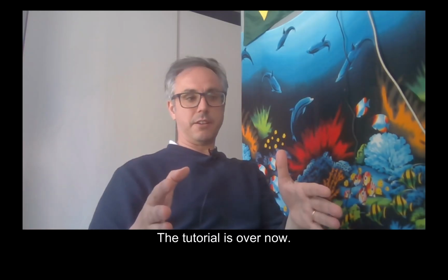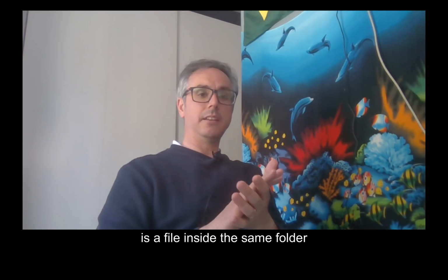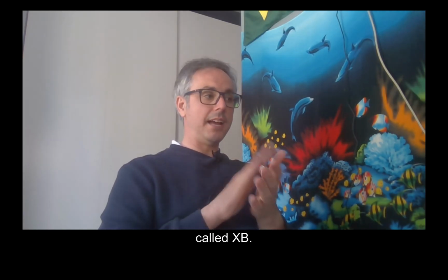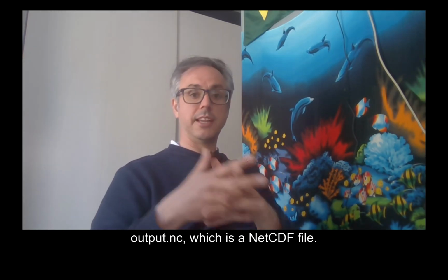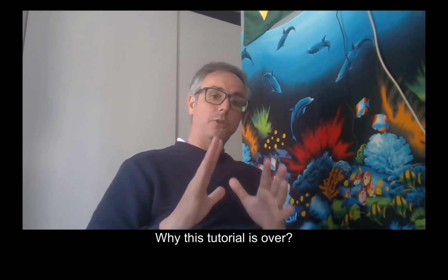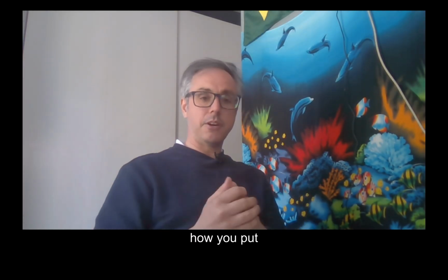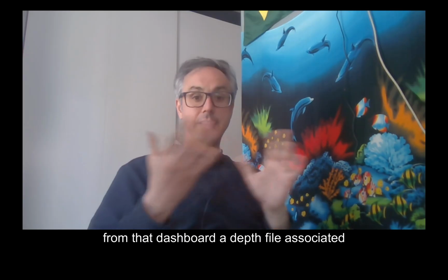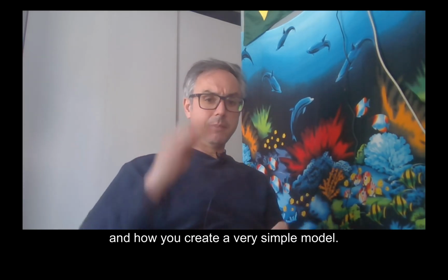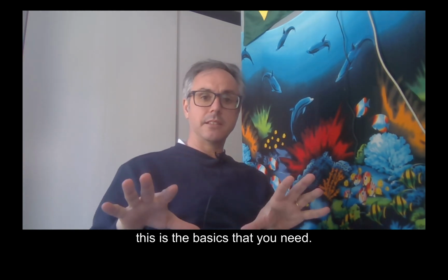The tutorial is over now. I'm just going to let it go. And what we'll have at the end is a file inside the same folder called xboutput.nc, which is a netcdf file. Why is this tutorial over? Because I just wanted to show you how you create a grid, how you create a depth, so how you put from Delft Dashboard a depth file associated with that grid, and how you create a very simple model. The JSON file, the tide file, this is the basics that you need.